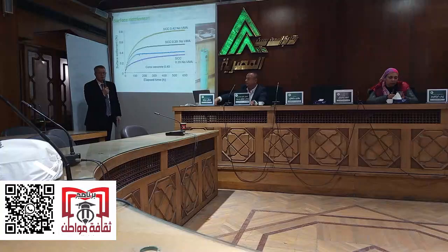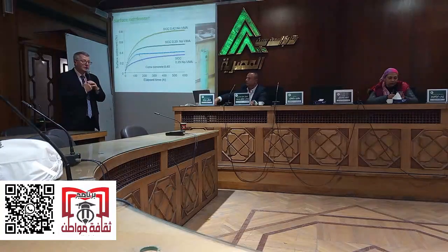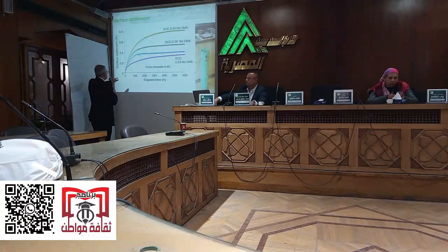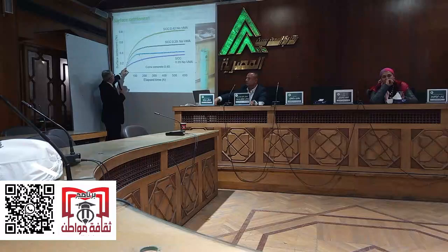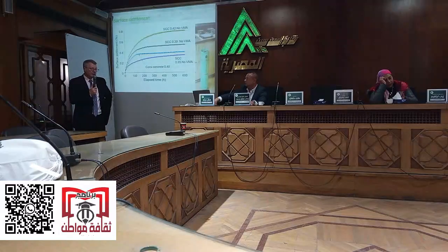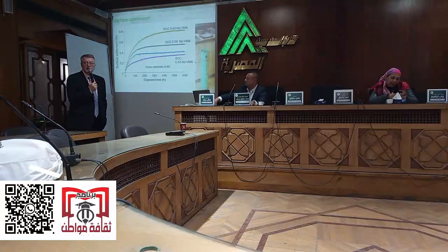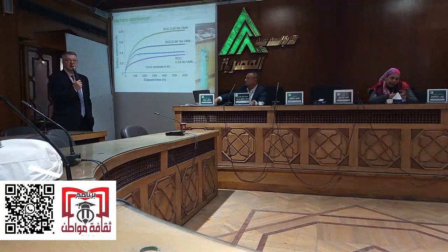So for example, in the black, you have conventional concrete, 150 millimeter, vibrated, and you see that the settlement is fairly low, not black, in pink. This is expressed as a percentage of the height, so 0.3% of the height. So 0.3% of the height is about 1.8 millimeters. The one on the very top in yellow, it's 0.42 water cement ratio without any viscosity modifier admixture. And you can see the settlement is 0.8.